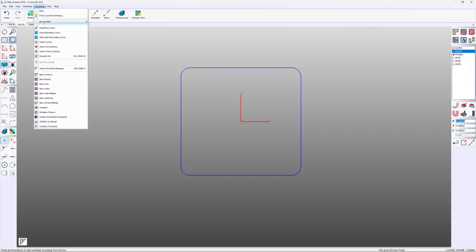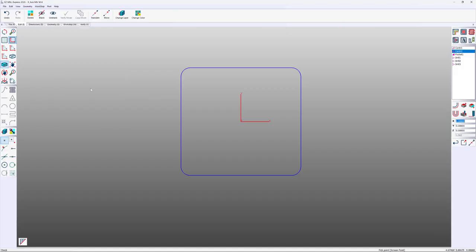Go to work step, define path. Come all the way down to generate geometry. Go to work step. And we're going to delete all links. So our curve is still there. It's still alive. We can change the way that curve looks up here on this control tab. But now I got to shorten it up for the tabs. So we'll verify again.